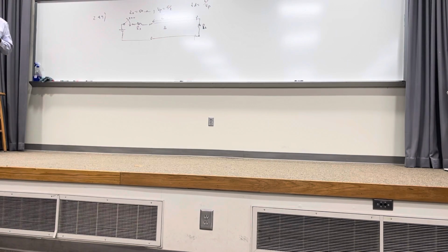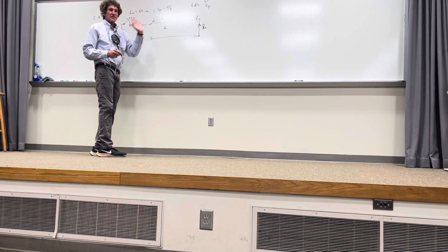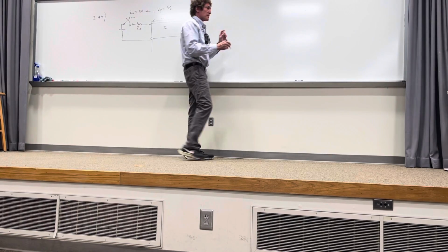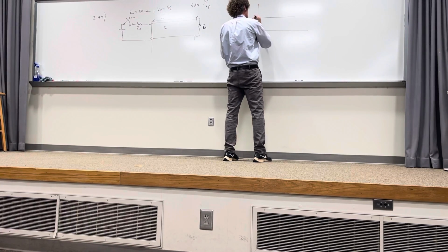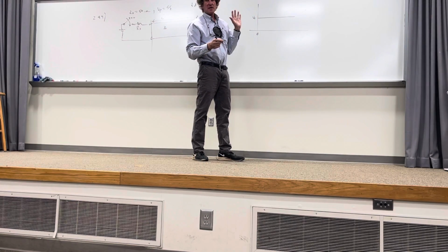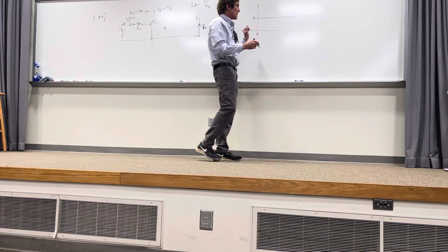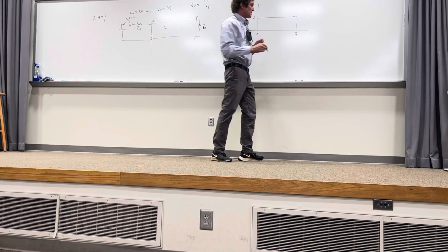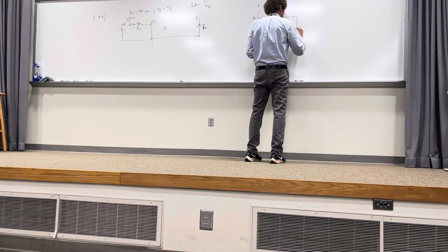So I'm going to try to explain this. We don't know the length of the line. But here's what we do know. We have a pulse diagram that looks like this. It starts at 0. I'm assuming this is the measurement of the voltage at the load end. And at 7 nanoseconds, there's a discontinuity, something that goes down, changes state.